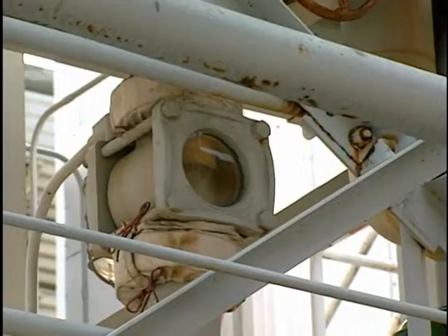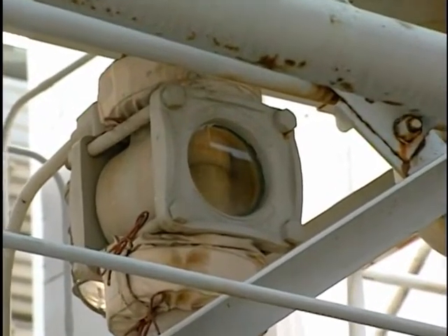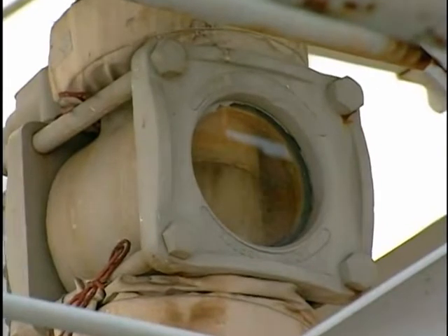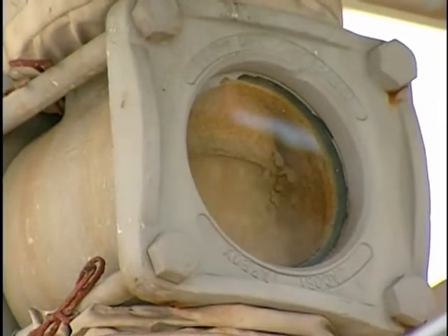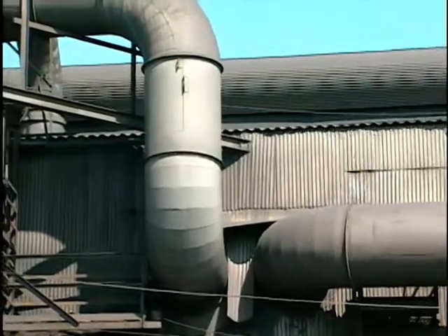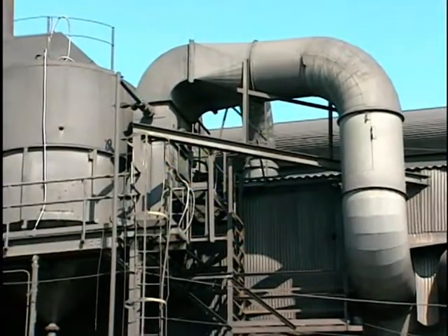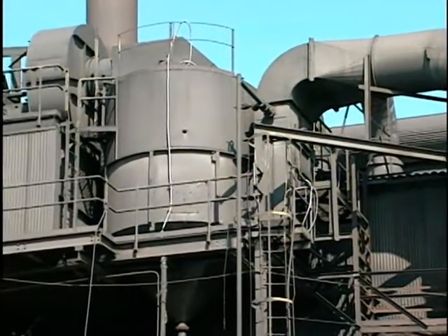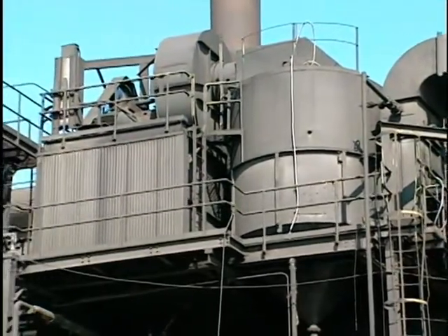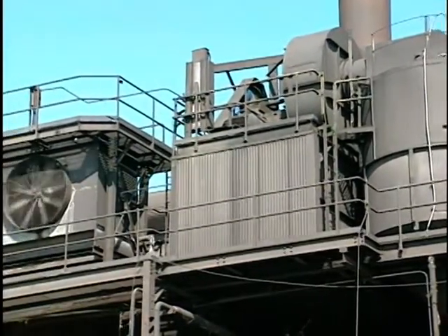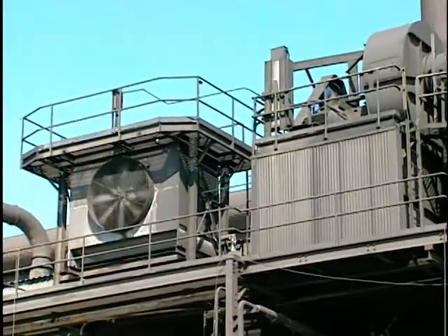In absorption processes, gaseous contaminants are removed from a gas stream by transferring them to a liquid. That liquid is usually water or an aqueous solution that contains chemicals selected to react with the absorbed contaminants. Absorbers can be designed to operate over a wide range of collection efficiency in order to meet specific emission limitations. Most systems operate with collection efficiencies of 70% to over 99%.